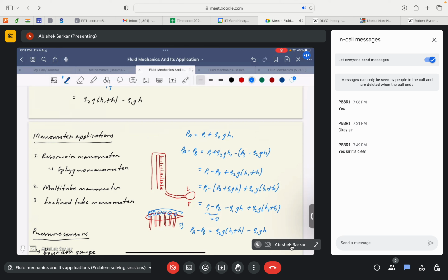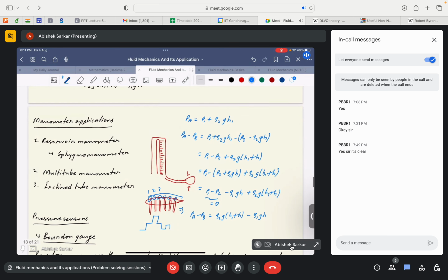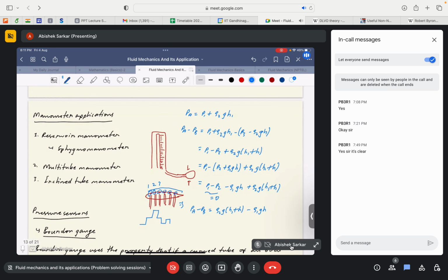So see that the pressure variation along the surface of the airfoil is a continuous process, right? It's not discrete. It won't have a discrete value, say at point 1, very much different from pressure at point 2 or 3. It's not like that. It's continuous, and that's why it's called a pressure field, right? The concept of pressure field comes into the picture. It varies continuously, right? There cannot be a distinct rise or fall, like the one being shown in the manometers.